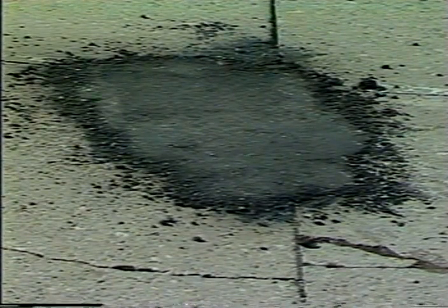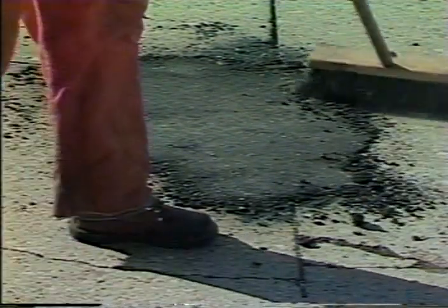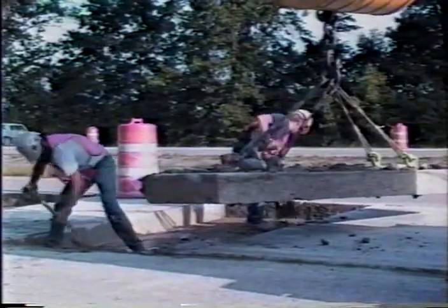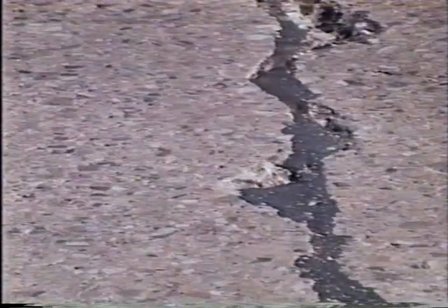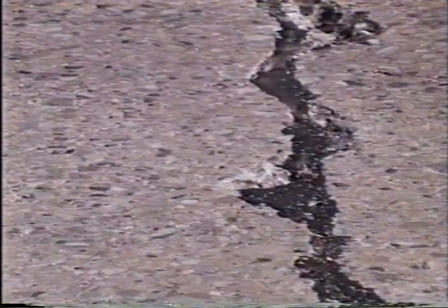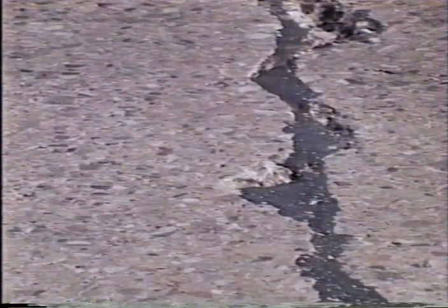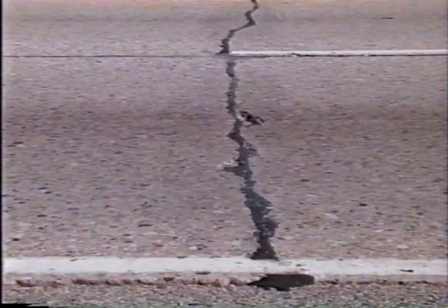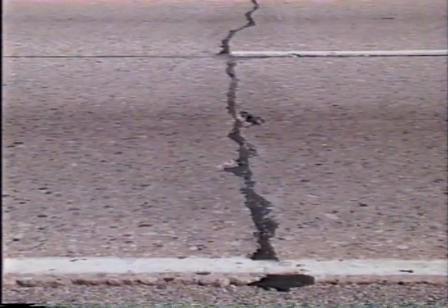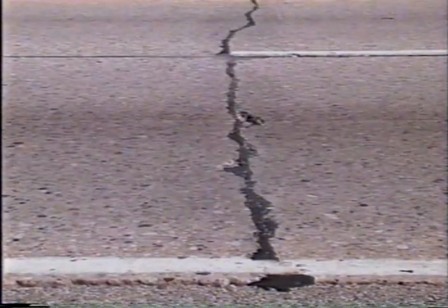For example, high-severity spalls at joints should be filled and compacted with bituminous patching mix. Shattered slabs that are rocking should be replaced. Faulting greater than 1/4 inch may need to be removed when a thin separation material is used. Faulting is not a problem, though, when a thick separation layer is used, such as 1 inch to 1.5 inches of asphalt concrete.